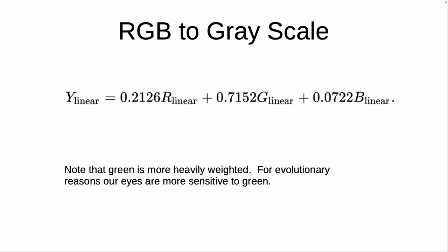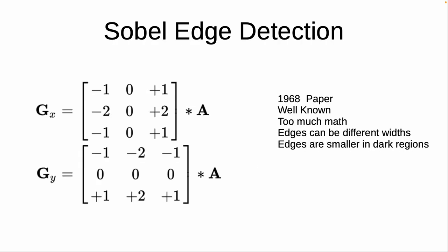For edge detection, a lot of people are interested in edge detection. A lot of people use Sobel and grayscale, so it's basically pretty simple multiply to convert to grayscale. And of course the green is weighted more heavily. Yeah, there's some tricks you can do on FPGAs to use slightly different coefficients and shrink the size of your multipliers. Sobel edge detection, very simple. I'm convinced you can do better than this on FPGAs.